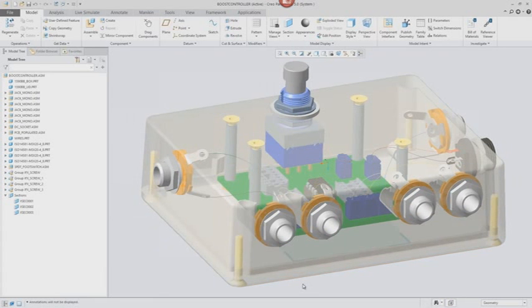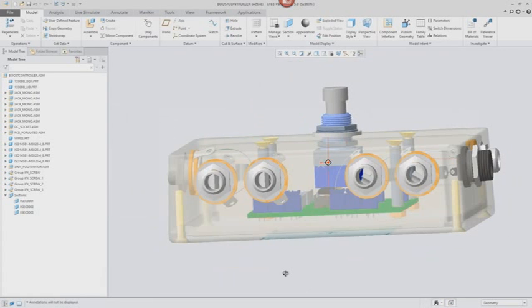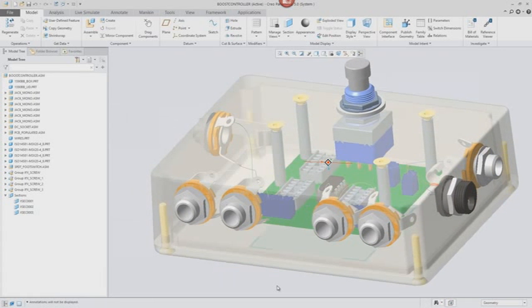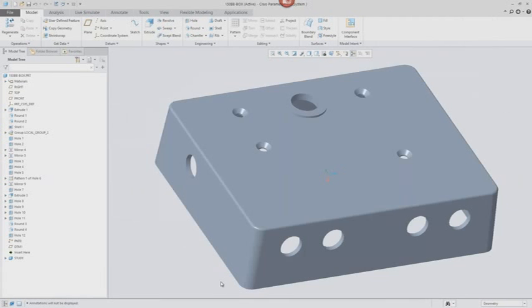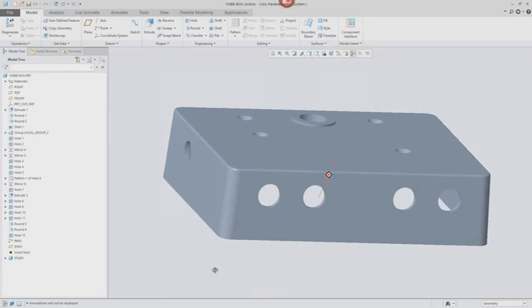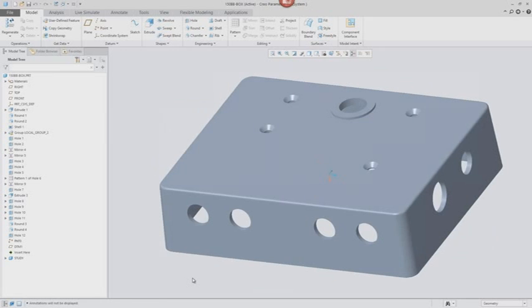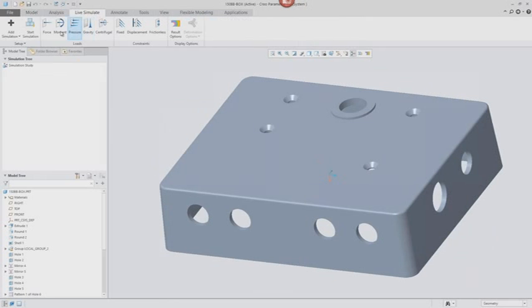Traditionally, since this is something that's going to be stepped on and has to withstand the stomping that a musician is going to do throughout their whole set, this might be made out of something like bent sheet metal. But I want to explore an alternative design, maybe make this out of ABS, maybe 3D print this in plastic, or maybe it's just cheaper to make this in plastic. But it's important that this still holds up to the structural impact that we're going to put this under as it goes through its life cycle. I'm concerned with the force of someone stepping on this, and that it might compromise the housing and maybe snap this in half.